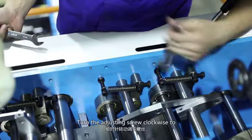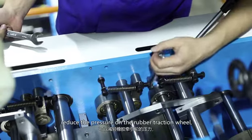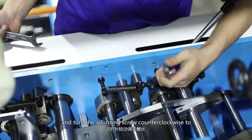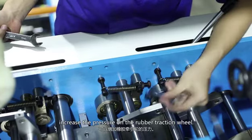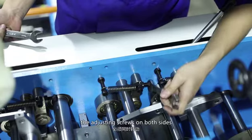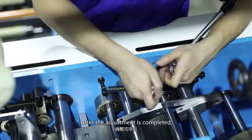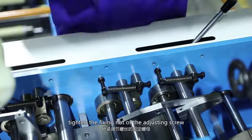Turn the adjusting screw clockwise to reduce the pressure on the rubber traction wheel, and turn the adjusting screw counterclockwise to increase the pressure on the rubber traction wheel. When adjusting the pressure, the adjusting screws on both sides must be turned at the same time. After the adjustment is completed, tighten the fixing knot of the adjusting screw.